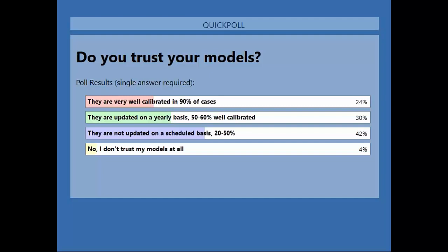I started by saying that we generally bring GIS data inside our model to create a physical representation of the system. The way that we do that inside WS Pro is by using the Open Data Import Center, where we can choose the category of the object that we are going to import, and the source type, which can be a shapefile, MapInfo, or a CSV file. And then we cross-match the object fields inside WS Pro with